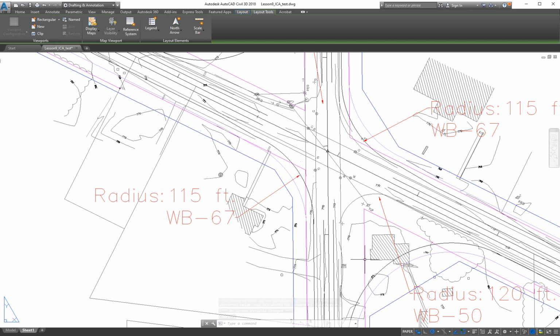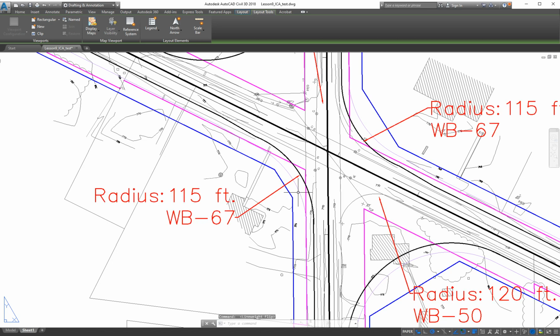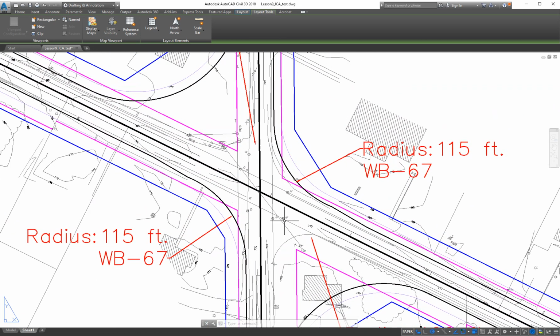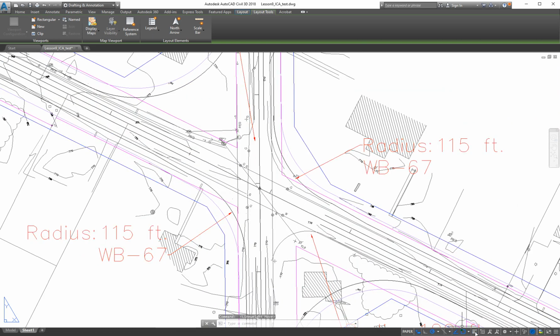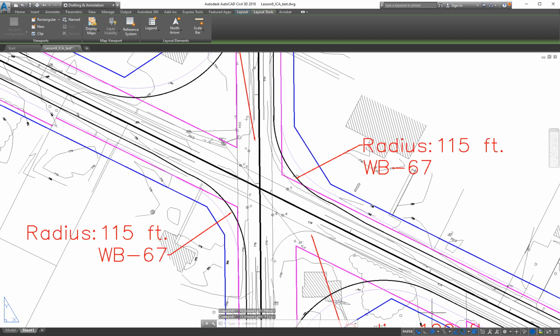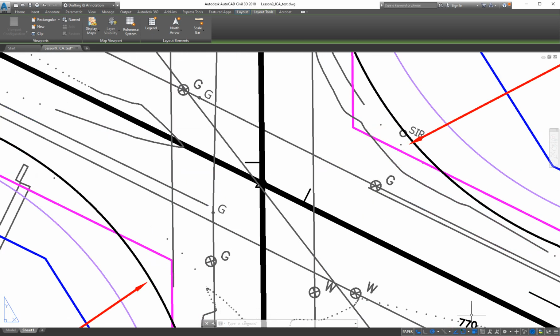To see these a little bit better, there are line weight scales, and this is the button down here, show or hide line weight. I think the default is it hides it, but sometimes it's easier to figure out where you are if you show it. I'm going to turn that on. Ooh, look at that. The line weights that you plugged into your layer manager, you don't always see them because sometimes they get confusing, and you can turn them off. That's how you turn off the line weight. Here's how you turn them on, right? Like the center lines, we use these great big bold lines. Sometimes that's just a little too busy. Maybe if I'm doing some delicate drafting in here and trying to snap things very carefully, I want to turn that off.